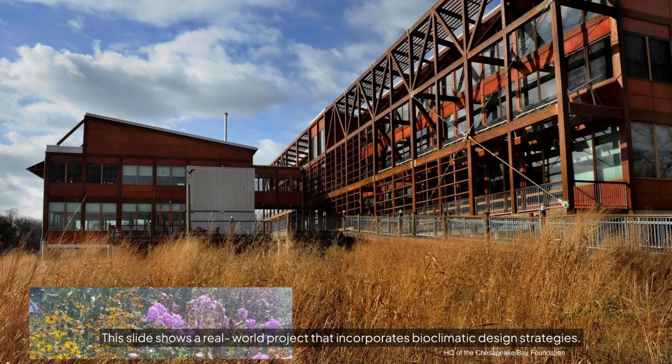This slide shows a real-world project that incorporates bioclimatic design strategies. The headquarters of the Chesapeake Bay Foundation opened in 2001 and received the world's first LEED Platinum. The building shape and the strategic placement of clerestory windows capture prevailing offshore winds for natural ventilation during mild seasons. The clerestory windows support not only cross ventilation but also daylight illumination.